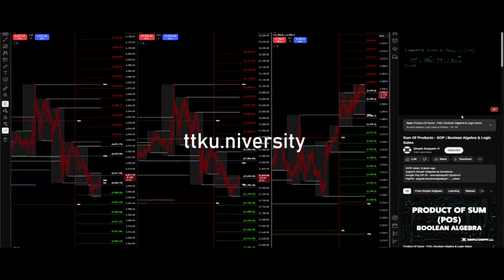So what is a standard sum of product expression? A standard sum of product expression is the one in which all the variables in the domain appear in each product term. So the standard sum of product expression would be something like this: ABC or BCA or C A B complement. Now remember that the complement of a single variable is always allowed in all these expressions. So how do you convert a sum of product expression to a standard sum of product expression?